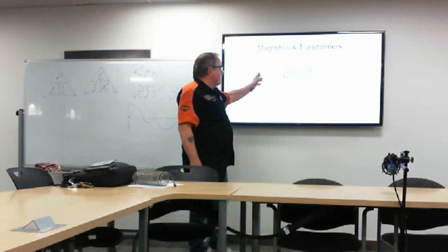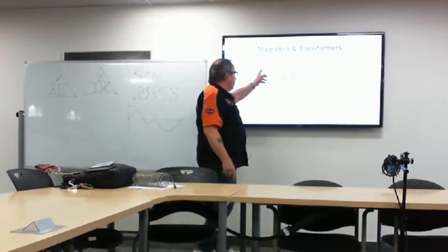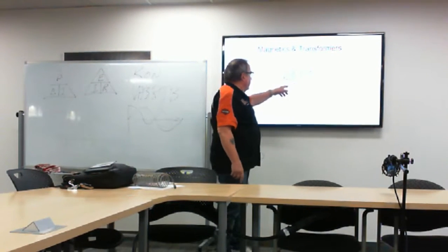So this is an example of a transformer. A transformer has two sides: primary side, secondary side. The primary side is the side to which you attach the source. That's the side you're powering. What you're getting out to this side is the result of that relationship. So we have a certain current here, and the iron core magnetic field, this field is changing direction back and forth. It's creating an AC current in this side. And as the current flows, the voltage is created across this load.